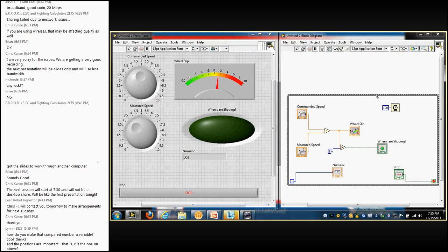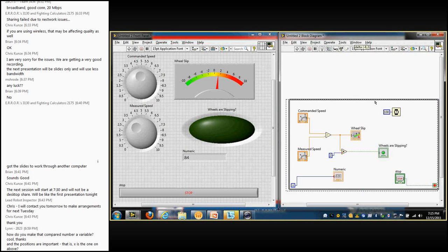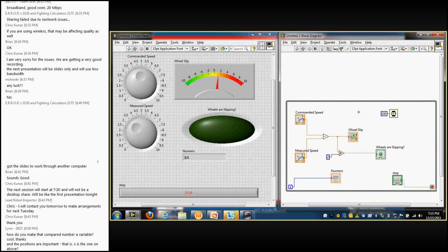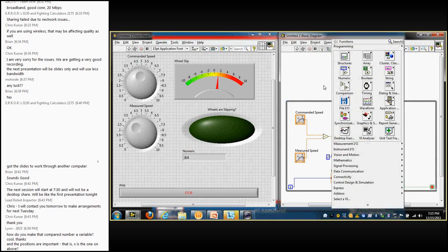If you're ever losing communication with your robot as your program starts running, it's not all that unlikely that you might have a loop that's running unbounded like this, that's kind of hogging up all the time that should be being used for communication back to your computer. So that's one loop. The other loop I was going to show you is a for loop.